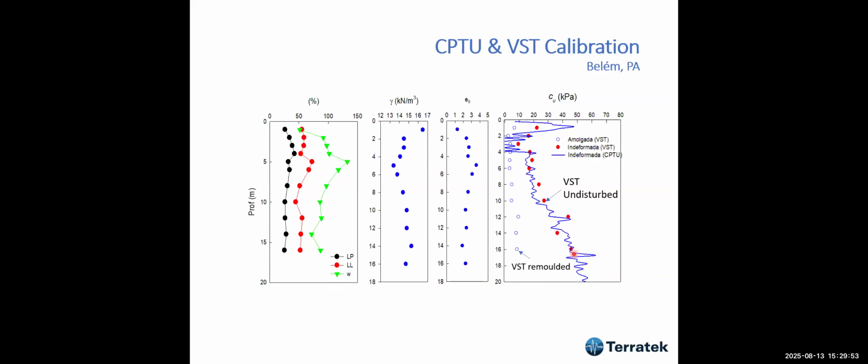This doesn't always take place, but we always should, when we are dealing with soft clays, do CPT and a VST very close.